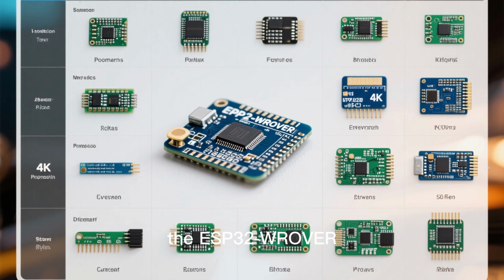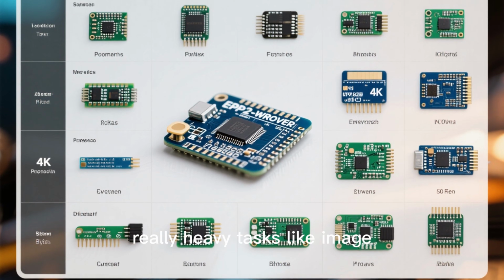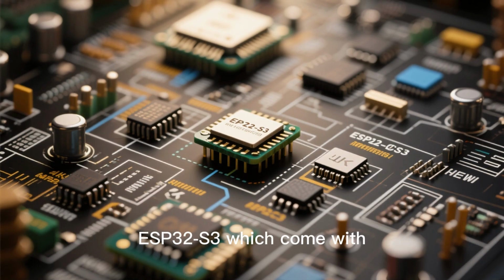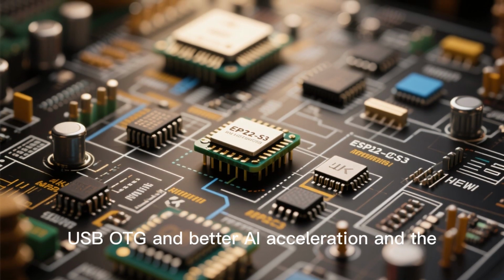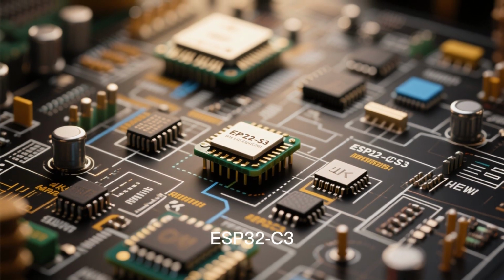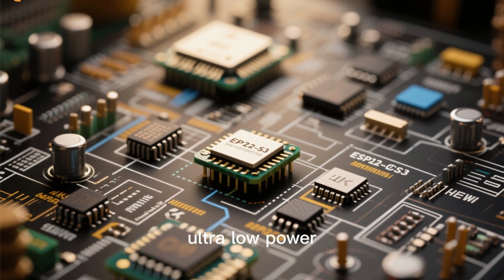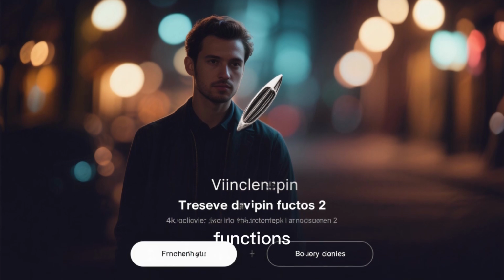Some of the most common boards are the ESP32 DevKit V1, the ESP32-WROOM-32, the ESP32-WROVER, which has extra RAM for really heavy tasks like image processing, and newer versions like the ESP32-S2 and ESP32-S3, which come with USB OTG and better AI acceleration, and the ESP32-C3, which has a RISC-V core and is ultra-low power.